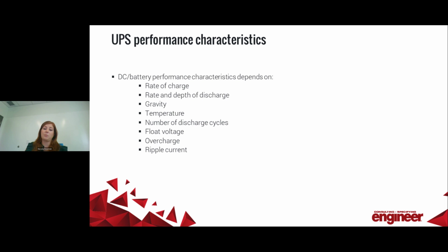So regardless of type, the temperature of your battery room is important. For every 15 degree Fahrenheit average annual temperature above 77 degrees Fahrenheit, the life of the battery is reduced by 50%. So it's really important to coordinate your battery shipping with the manufacturer and your storing with the owner. When you're specifying your battery type, be cognizant of space requirements, battery containment requirements, smoke detection, ventilation, temperature requirements, and the room rating per IBC Table 509 and the International Fire Code Table 1206.2.